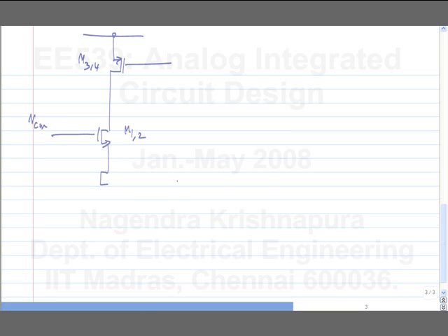This is at whatever value is necessary. So let's say it comes from a current source. Okay, current mirror rather. And the current mirror is designed to provide nominally a current of I naught in this. Each of M3 and M4 carries I naught by 2. So the combined transistor carries I naught, or supposed to carry I naught. And this carries I naught also. Okay.